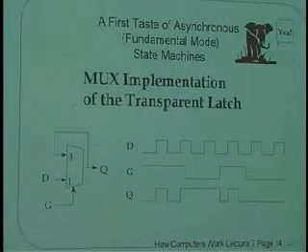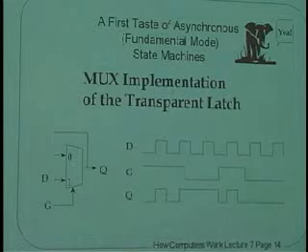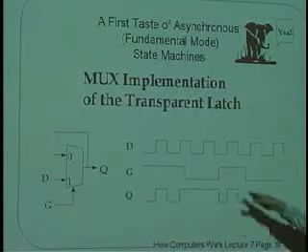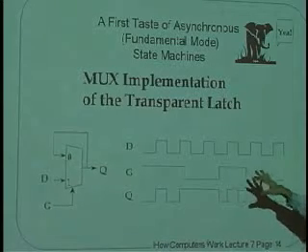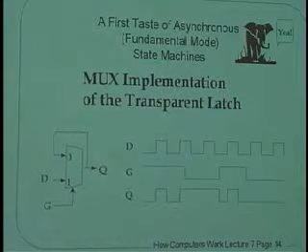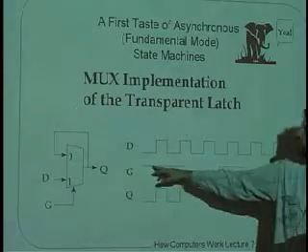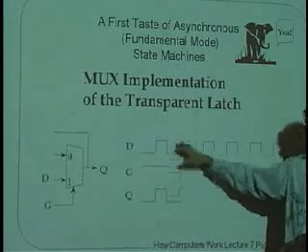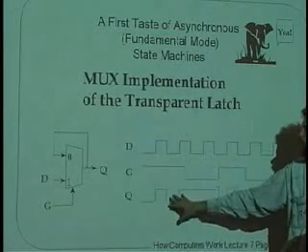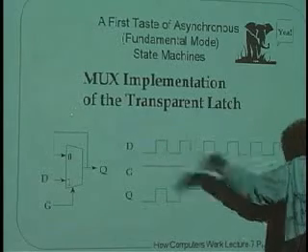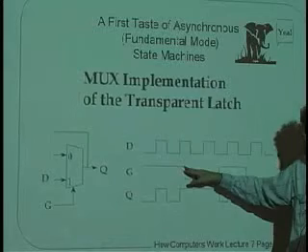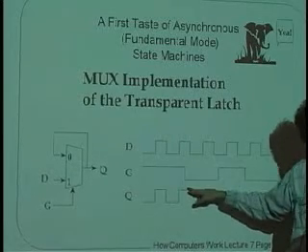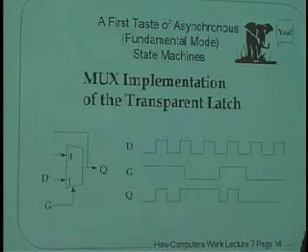Now, we don't have a register yet, okay? We don't have this flip-flop that's sensitive to edges. We're building something more primitive, which is this thing called a latch, a transparent latch. Now, why is it called a transparent latch? Because when the gate is high, it's like a window, and Q is a transparent copy through glass of D. However, it latches when G goes low and holds on to whatever the last value of Q was.